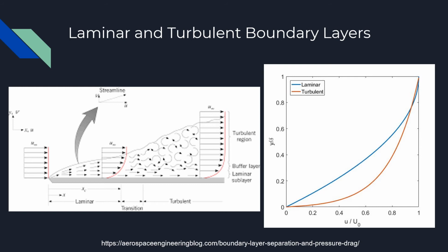In laminar flow, everything is orderly and fluid particles do not interchange layers. In turbulent flow, the fluid particles move more chaotically, including perpendicular to the flow direction. This results in turbulent boundary layers being larger than laminar layers and creating more friction drag. While turbulent boundary layers are larger, the velocity gradient in the boundary layer increases faster.